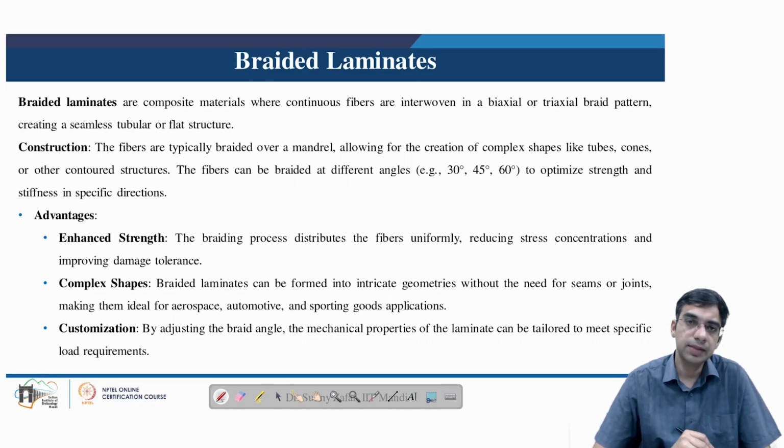stiffness in specific directions. The advantages that braided laminates offer include enhanced strength, which distributes fibers uniformly, reducing stress concentration and improving damage tolerance.